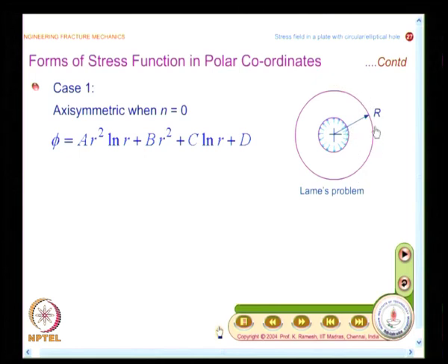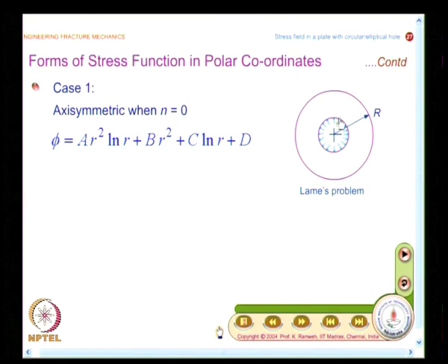And you have a thick cylinder, the wall thickness is considerable, and if you have to find out, you will have to go by theory of elasticity. And what is the kind of domain here? We have discussed what are simply connected and multiply connected objects. It is actually a multiply connected object, and in this case just satisfying the Bi-harmonic equation and boundary condition alone is not sufficient. You should also look at whether the displacement is unique when you go round the ring once.